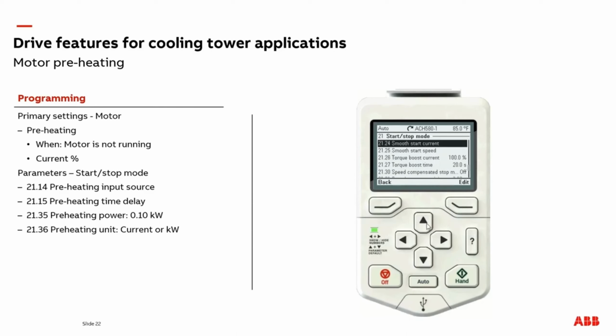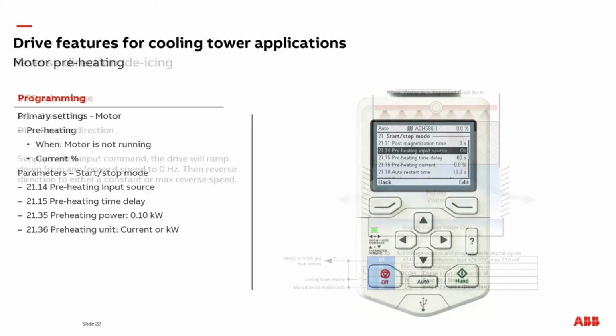Select Save, scroll up to enable motor heating, which you cannot adjust the power amounts while it's enabled, and activate it. When the motor heating is activated, a warning message will be displayed on the keypad indicating that it is active, as well as an icon will show up by the drive name. You can hide this screen to continue making adjustments.